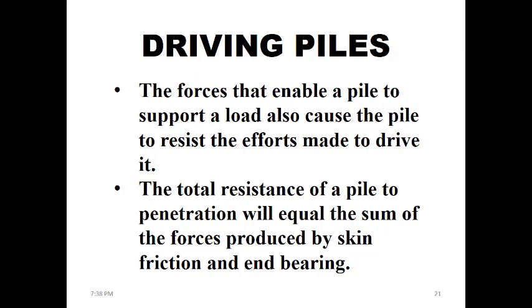For the forces that resist the driving process, you can think of it as the loads that will support the structure in its place, or vice versa. The forces that will keep the structure in place are the forces that you have to overcome in order to drive the pile into the media, right?